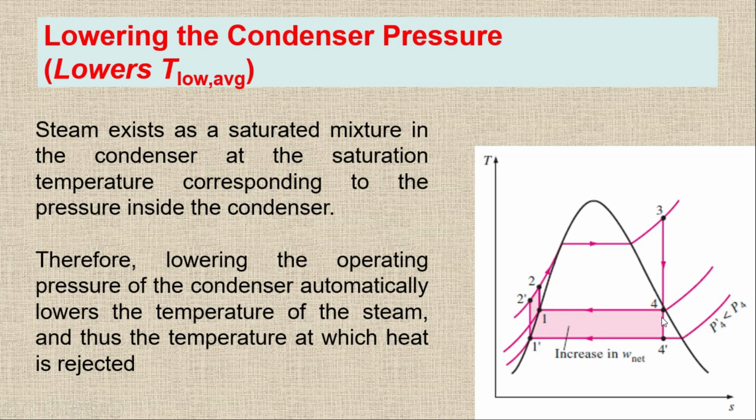So if I'm going to decrease the pressure, so we will get this one from here to here, from 4 to 4 dash, we will get some extra work output. So this is the extra work output. On the other hand, the heat input requirement also increases.